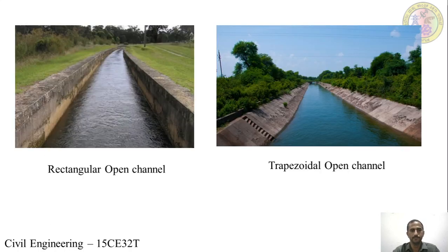Open channels are of rectangular, trapezoidal, semicircular or V shape. These open channels can either be lined or unlined. To prevent the seepage loss, they should be lined.